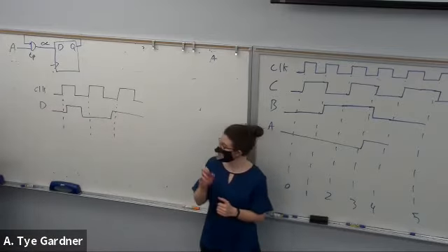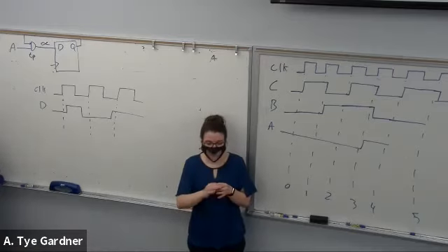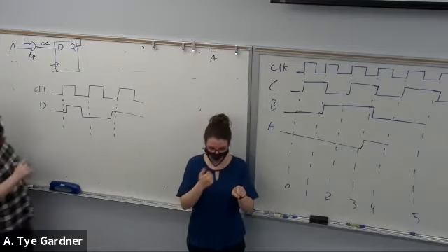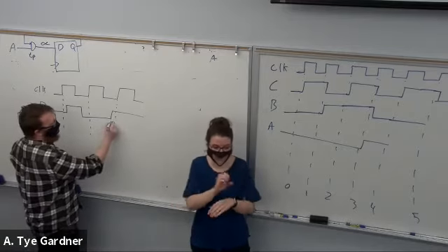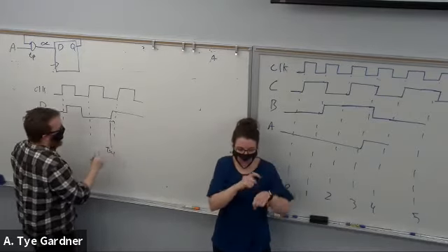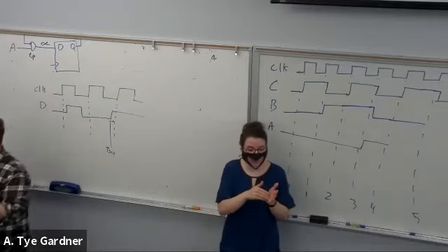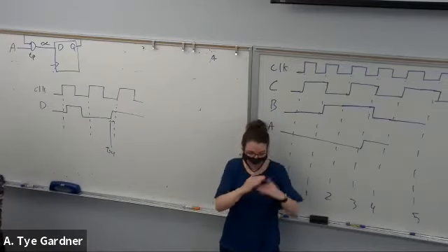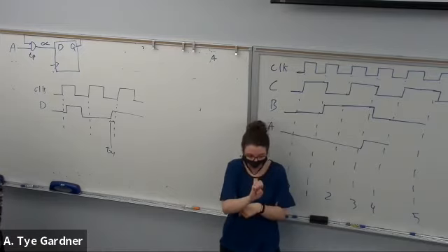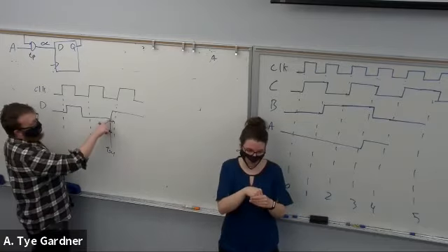So there are a couple different kinds of delays, and setup and hold time are something we're concerned with. Setup time is the minimum amount of time that you need to have the inputs stable before the clock. You need to set up your inputs. So here is setup time.